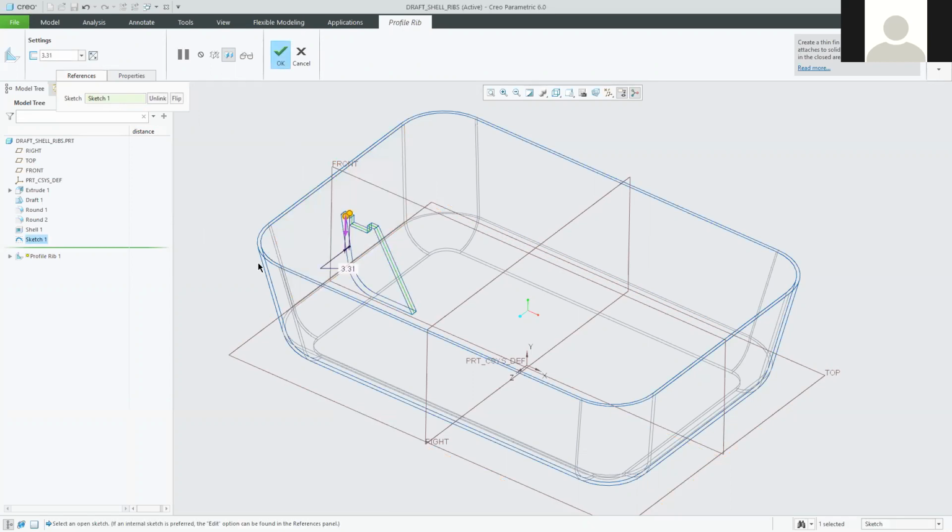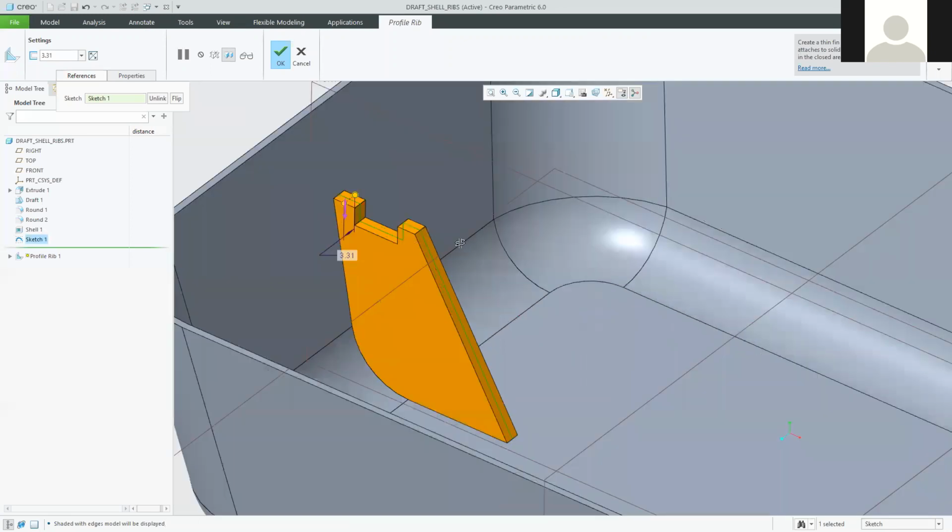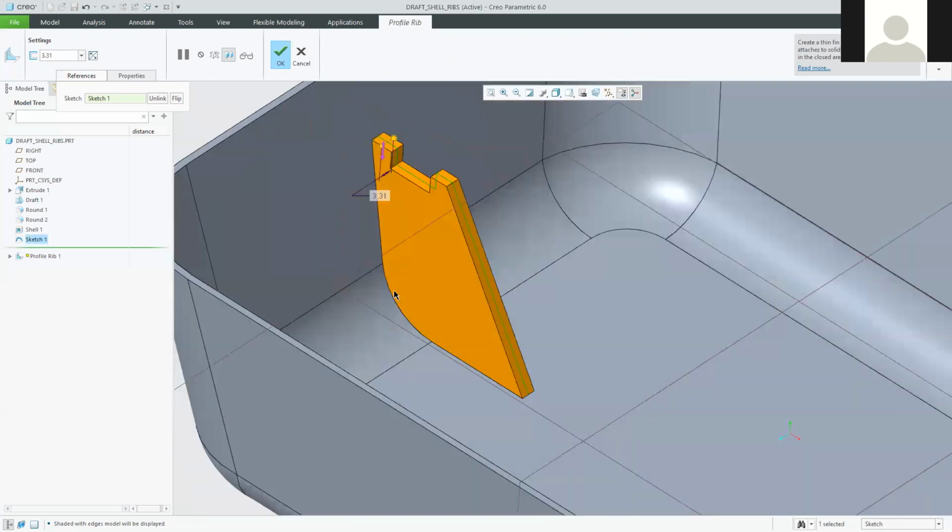And at this point, just because there might be a bit of ambiguity in what I'm looking at there, I'd probably turn the system back to shaded with edges, so that I've got what I consider my default display style. So click on display style there, switch it back to shading with edges. That's more like what we've become used to. So you can see the preview there.